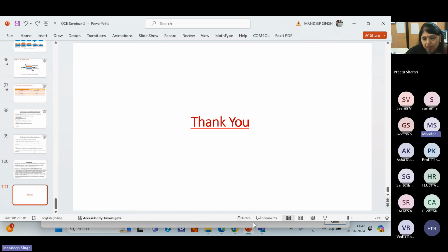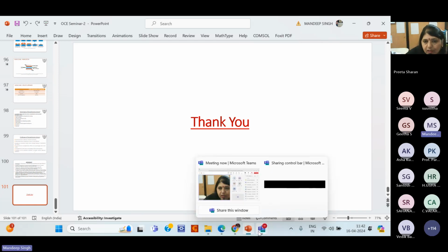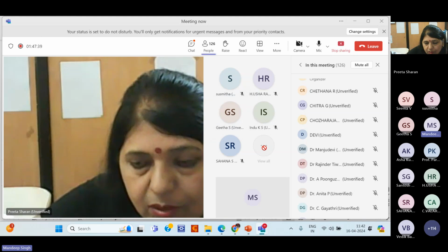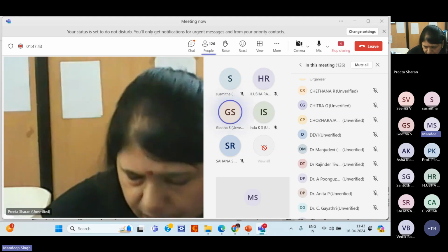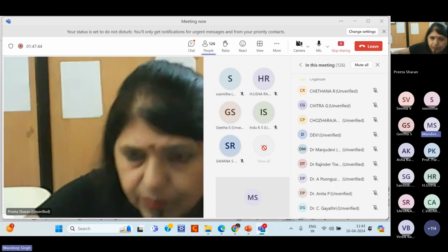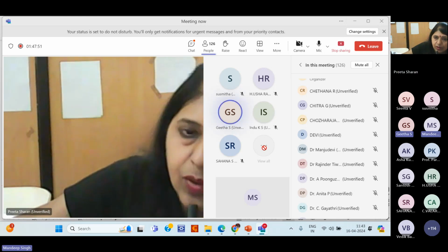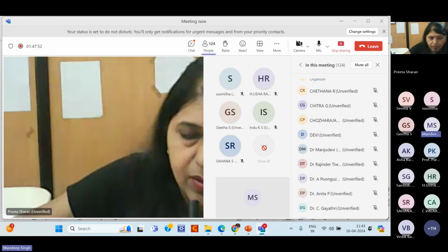It again depends upon the interaction with the analyte. If you are using dielectric on the top, analytes can easily interact, because dielectrics are porous in nature. But if you need more confinement, then MIM is better. It depends upon the application. For a device, MIM is better, but for a sensor, dielectric-metal-dielectric is better.